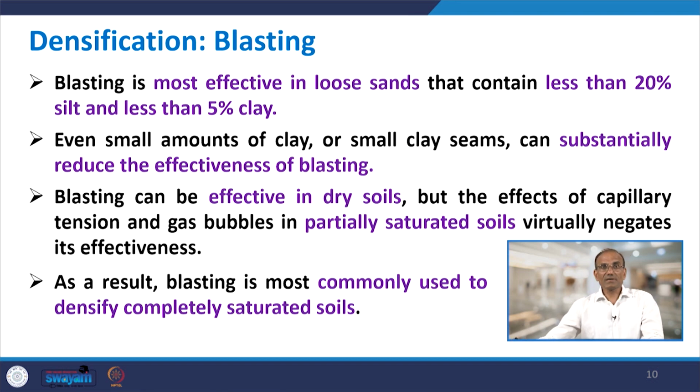Blasting is most commonly effective in loose sands that contain less than 20% silt and less than 5% clay. Even a small amount of clay or small clay seams can substantially reduce the effectiveness of blasting. Blasting can be effective in dry soils, but the effects of capillary tensions and gas bubbles in partially saturated soils virtually negate its effectiveness.